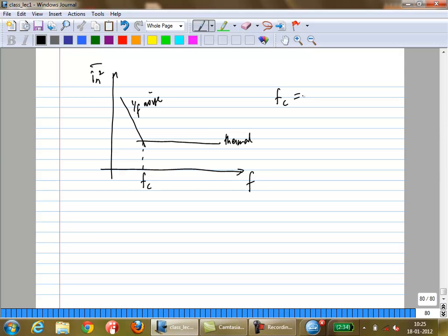You can show that this is approximately K 1 over F by 4 kT gamma times Ft. So now definitely in analog circuits, this is the band of interest, from DC to tens or hundreds of megahertz. So you are definitely interested in flicker noise; it is very important.